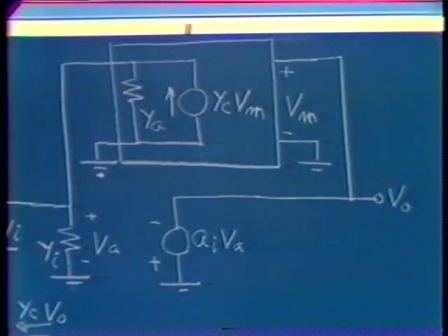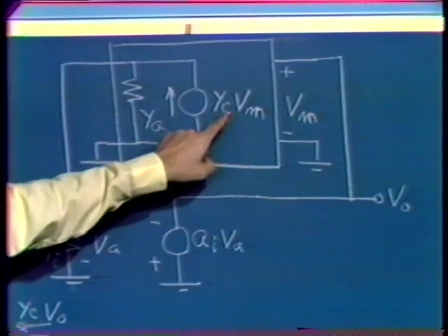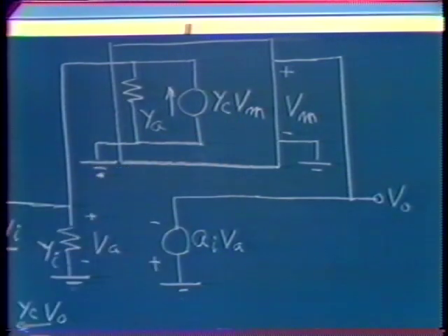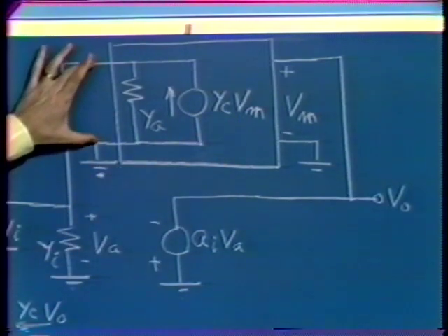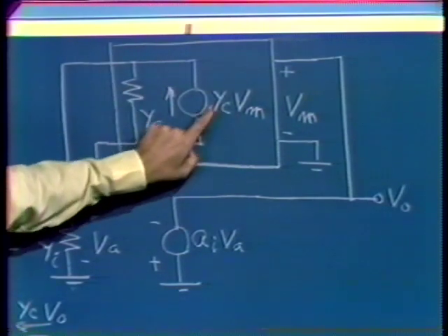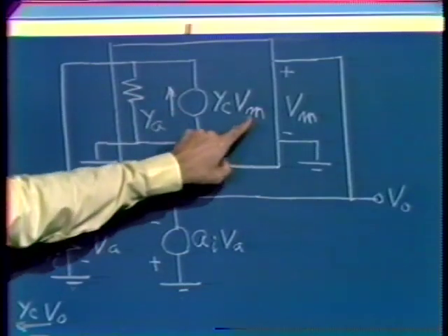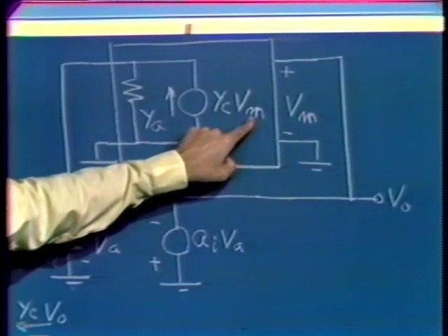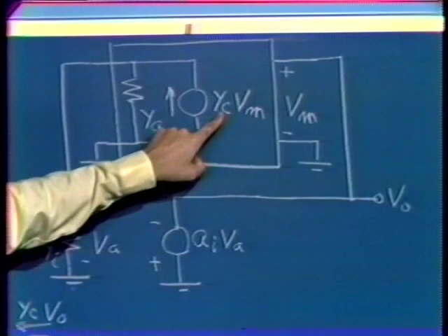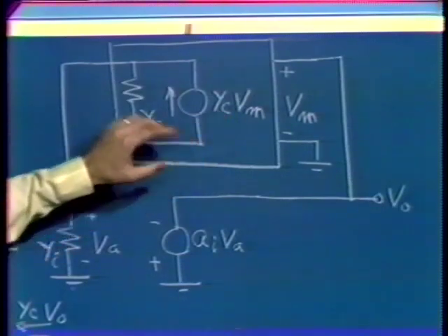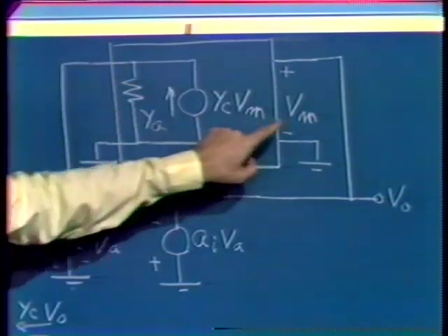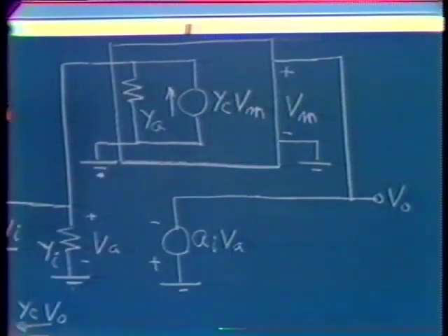So we can model our two-port at this side as this admittance and this dependent current source. Of course, to evaluate the quantity Y sub C, we'd perform an experiment where we'd incrementally short this port of the two-port and would then measure the relationship between that short-circuit current that we observed and the voltage V sub n. We'd find that Y sub C was simply the ratio of the short-circuit current to the voltage applied to this port of the network.